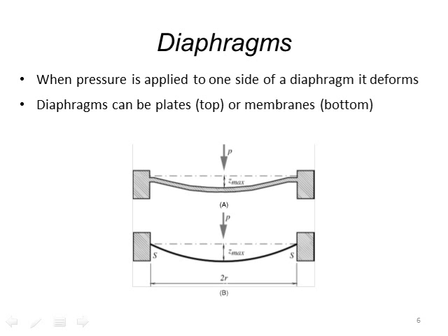So the dynamics of the bending is very, very different, and therefore the displacement that you have is very different. So the displacement as a function of pressure is going to be very different. So you have to be quite careful in whether you use a plate equation or a membrane equation in order to relate the deflection of a membrane in the center with respect to the pressure.